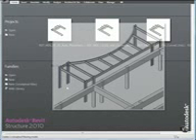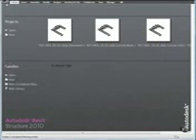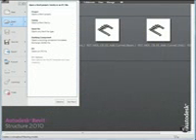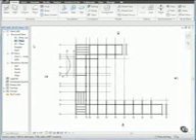In this lesson, you will sketch a beam system to frame the entryway roof. Click on the menu browser and select Open Project. Then open the file rstmdl-bs02 sketch. When the file opens, under Structural Plans in the project browser, double-click 02 floor. Then zoom in on the entryway of the structure.